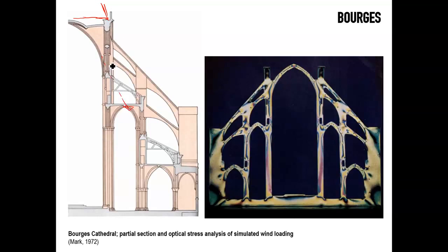Now, the purpose of all this external structure you often see in Gothic cathedrals is exactly that of absorbing directly all these forces from the vaults and somehow bypassing these internal walls, so that these internal walls can be reduced in depth.